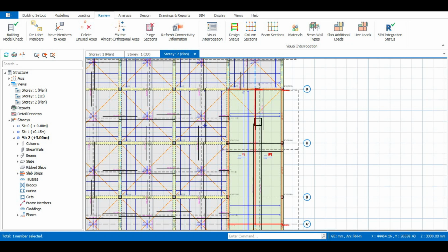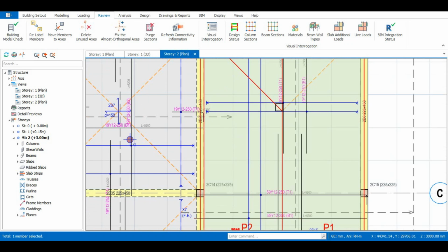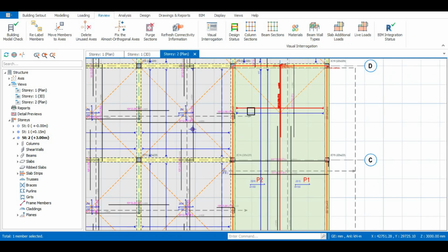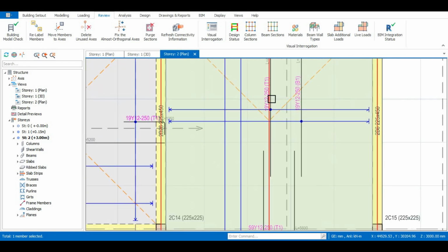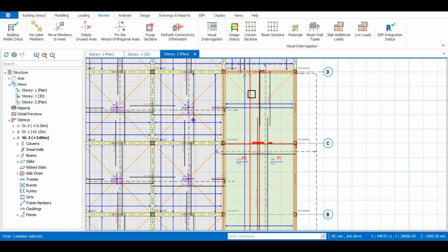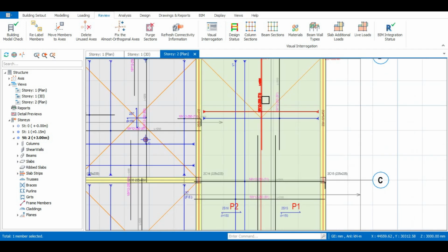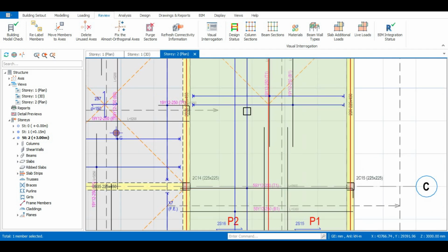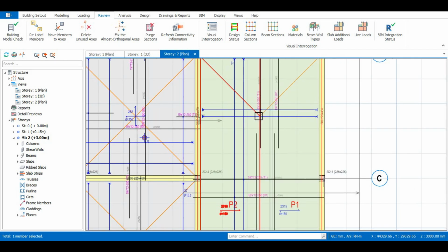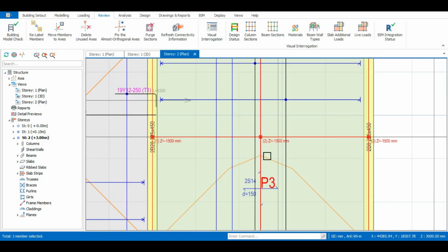In order to detail the ramps, you see that the length of the ramp can be divided into two, from here to here. Since we have 19 Y12 as the bar that is going to be arranged on this entire ramp, you can have 10 on one side and 9 on the other side. You can also have 10 on both sides, depending on how you want to execute your project as a structural engineer. It's based on your discretion as a structural engineer.